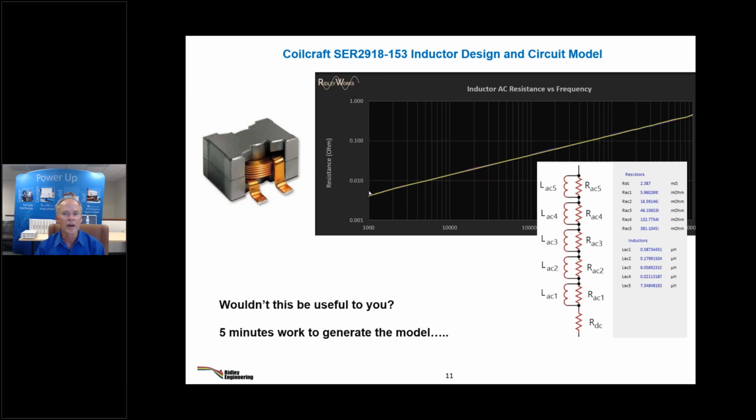Can I verify Fourier solution? Yeah, the Fourier solution. I see John has answered this. The Fourier solution just happens in the time domain. You only need Fourier if you're doing post-analysis. But you're hitting the model in the time domain. The switching waveforms are there. Okay, so you don't need any Fourier. That's the beauty of the time domain simulation.